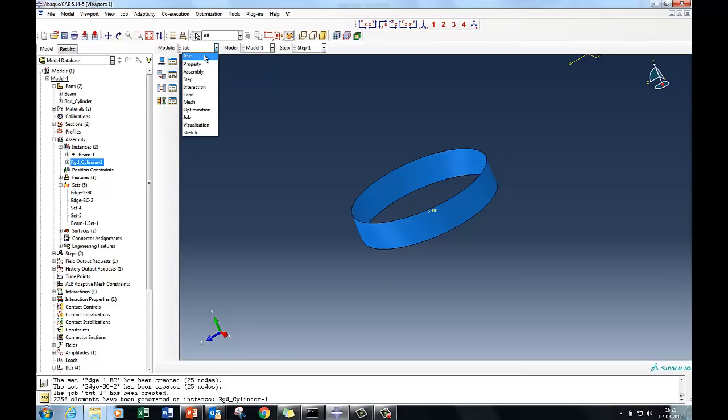So guys, what we have done is we created property assembly, and then we positioned the model properly, and then we defined the explicit dynamic time domain, then followed by the contact, then we meshed the part and load, and then we applied the load boundary conditions with the node sets for the beam, and then applied the displacement to the reference point of the rigid cylinder, and then we meshed the rigid cylinder part as well.